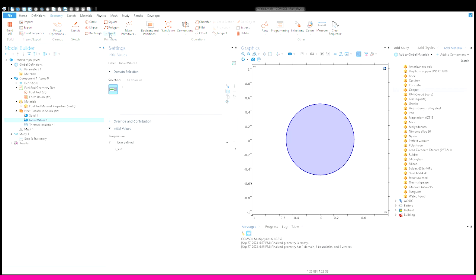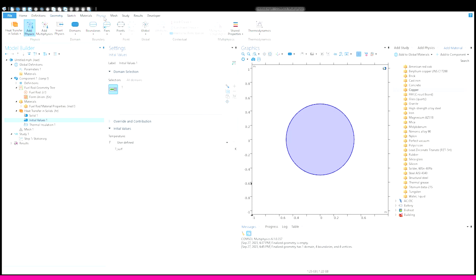And then in physics, now we need to add a couple things. So we have the boundary condition, which is a temperature boundary condition. We're just saying at this point, the temperature is this for all time. And of course, that is T-surf. It's user-defined, and then, like I said, the equation's always there. Temperature is always equal to that temperature T0, and T0 is here. So we've done that, and then of course the last thing we have to do is add a heat source, the nuclear decay, and that's just HV. And then I think our study should be good to go.